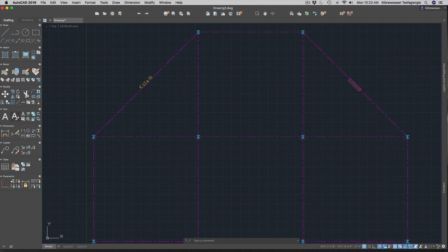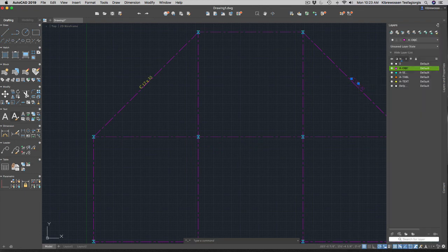If you feel this text height is too small, then you may go ahead and change the text height to a better value. So that's pretty much it. This is how you are going to proceed, and that text has to be on a text layer.